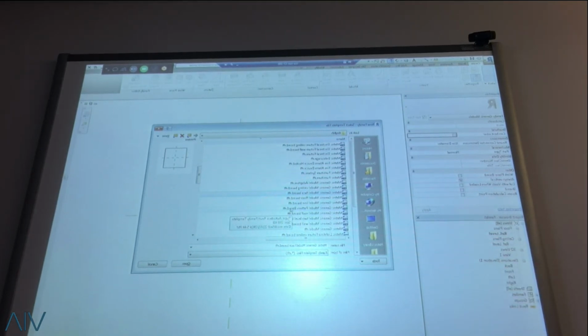Most of the time I would recommend that users, if you want to start with a template, do not add anything hosted on something, because if your wall, roof, or whatever is deleted, the hosted object is also automatically deleted. That's one thing to be careful with, because sometimes people like to host stuff on a wall. Let's say, for example, a little electrical outlet hosted on a wall.